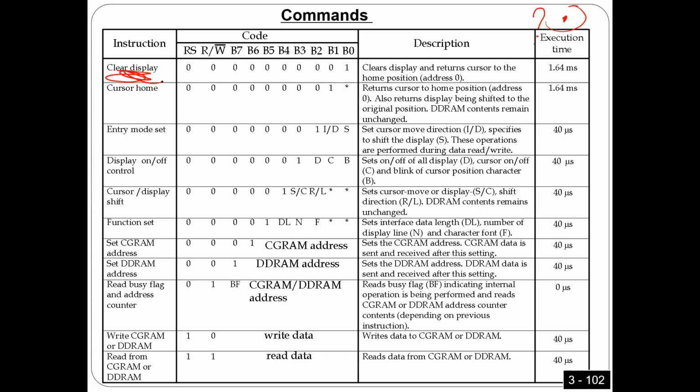Also, guys, although I mentioned in the beginning, here I'm teaching one LCD. The good thing is that almost all of them work the same way. But you have to be careful. When you get an LCD, you have to look at its data sheet, because you may have to use different numbers for the commands, since these numbers come from the company that made the LCD.